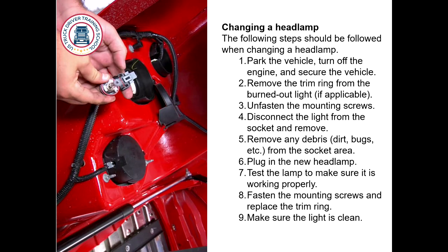Remove any debris, dirt, bugs, etc. from the socket area. Plug in the new headlamp. Test the lamp to make sure it is working properly. Fasten the mounting screws and replace the trim ring. Make sure the light is clean.